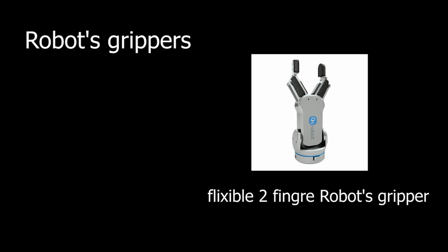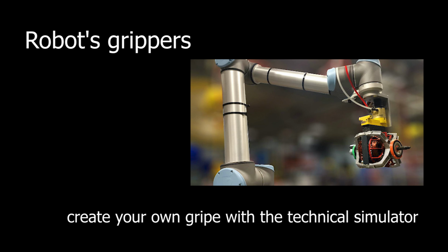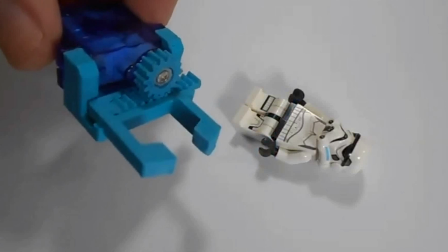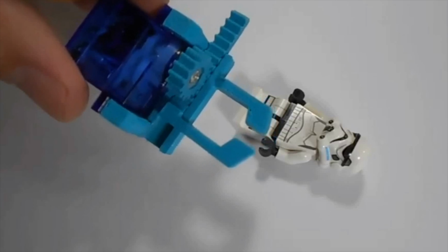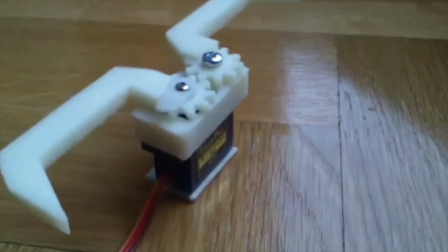What are robotic grippers? A common form of robotic grasping is force closure. Generally, the gripping mechanism is done by the grippers or mechanical fingers. Two-finger grippers tend to be used for industrial robots performing specific tasks in less complex applications. The fingers are replaceable. Two types of mechanisms used in two-finger gripping account for the shape of the surface to be gripped and the force required to grip the object.